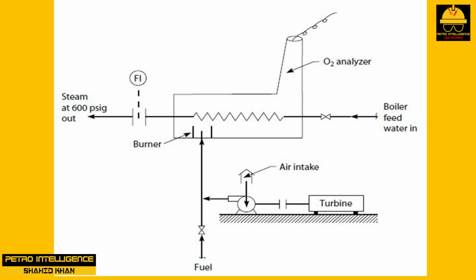No! We are going to adjust the speed of the FD fan to produce the maximum amount of 600 psig steam. In other words, we are going to maximize the heat to the process by adjusting the air rate. The point at which the steam production is at maximum is the point of absolute combustion. The oxygen content of the flue gas at the point of absolute combustion, where steam production is maximum for a given amount of fuel, will be the optimum.